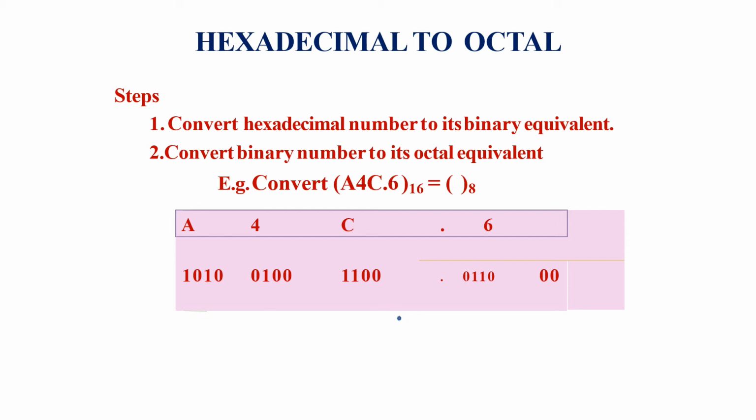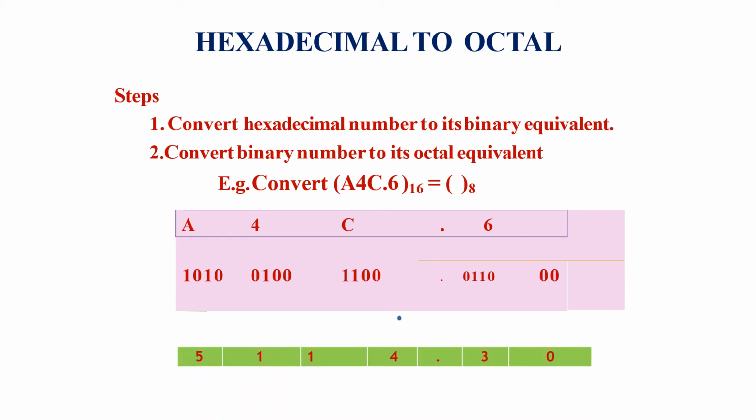We know how to convert from binary to octal. What you have to do is start from the LSB and group 3 bits as a group. So that is 0, 0, 1 as a group, then this 1 and this 0, 0 as a group, and then 1, 0, 0 as a group, finally 1, 0, 1 as a group. That is, for example, like this.